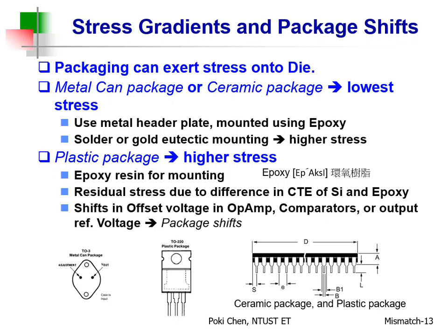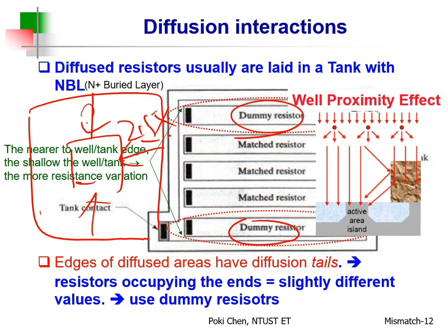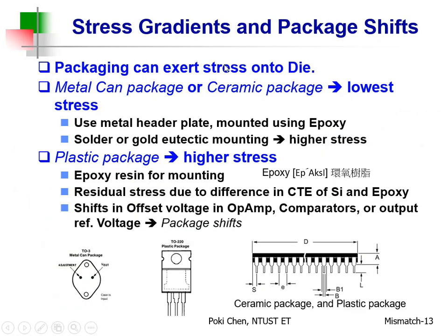I'm not telling you no device is allowed if they are close to a boundary. No. I'm only telling you no critical devices is allowed here. But some non-critical devices can be laid out here. Got it? It's not that nothing can be placed at the edge; just don't put the critical, more important ones too close. You can put the dummies or other unimportant devices there. Okay, then we need to get some kind of stress,